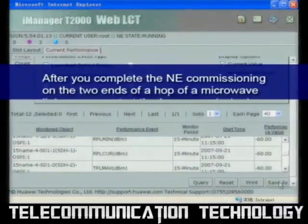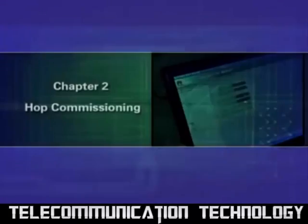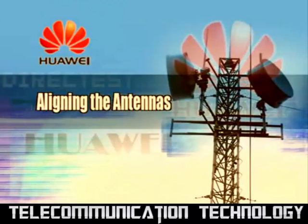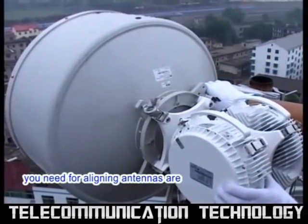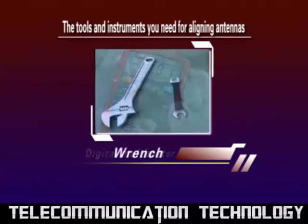After you complete the NE commissioning on the two ends of a hop of a microwave link, you can start the hop commissioning, including aligning antennas. Chapter 2. Hop Commissioning. 1. Aligning the antennas. The tools and instruments you need for aligning antennas are BNC cables, digital multimeter, and wrench.